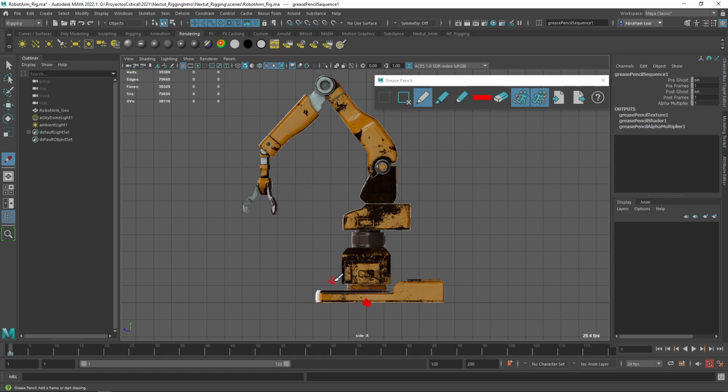Then I know that we have this section right here that just rotates around. So we're definitely going to have another joint right about there. Then this section right here also rotates around in the y-axis, so I'm going to have another one right there. After this one, there's really no more rotations until we hit this part right here on the top. In this area, we're going to have another joint, but this one is not going to have the rotation on this axis. It's going to be on this axis. Sorry, I believe this is the x-axis. It's going to be rotating on the x-axis.